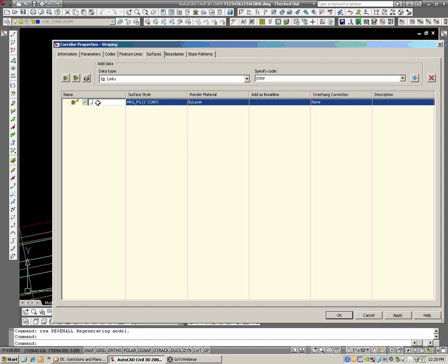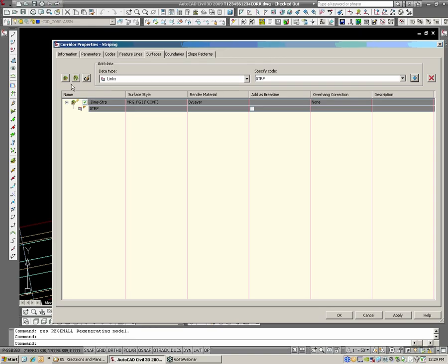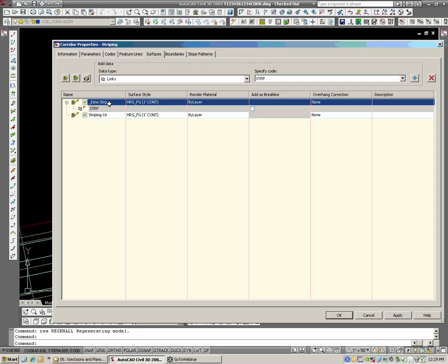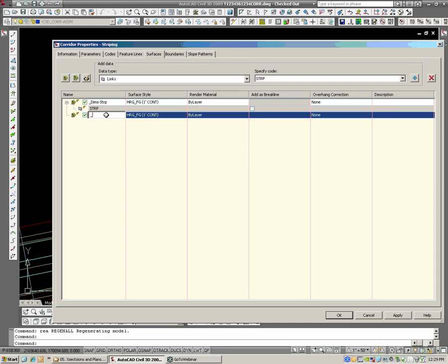Call this _dims strp. And the links we're going to add into this, since I coded it up for you already, I have the striping pieces coded separately from the right-of-way, so I'm going to add the striping links. Just that simple. Create another surface called _dims ROW. Yep.